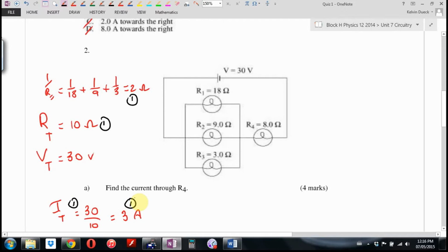Now, before I turn the page, because I have my circuit here, I'm going to fill a bunch of stuff in. Now that I know the current, 3 amps, 24 volts, I times R. Why can I go 6 volts, 6 volts, and 6 volts? Kirchhoff's law for voltage. Any closed loop has to end up back where I started from, as long as I always go downhill. Okay, so 30 minus 24 minus 6 in any of those forks.